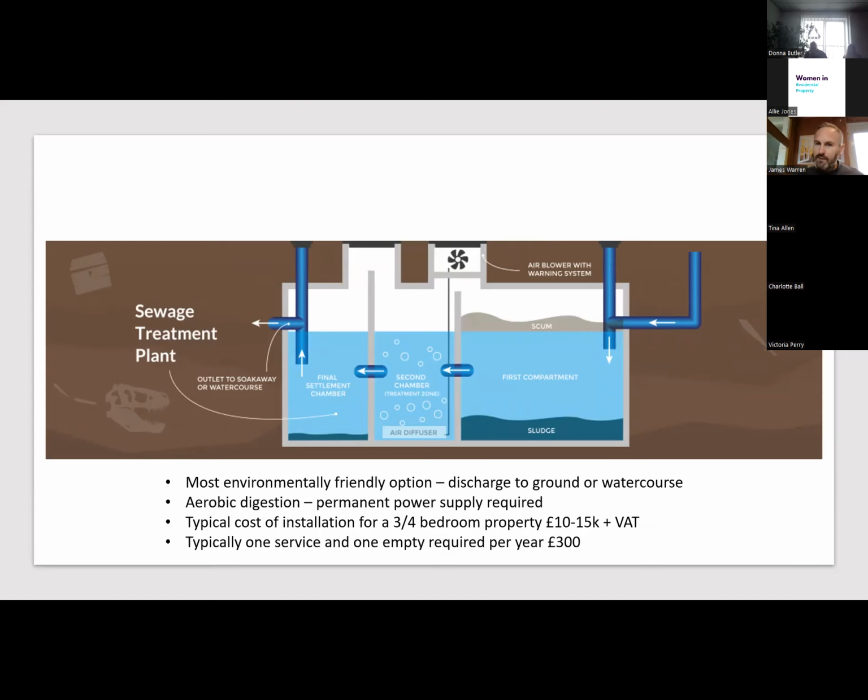And what I mean by that is, if we look at the first part of this system on the right hand side, I've labeled it first compartment. Its actual terminology is primary zone, but it's nothing more than a septic tank inside this housing. So in the good old days, you'd have a separate septic tank, then you'd have something called a clinker bed, which is where some treatment occurred, and then you'd have something called a reed bed, where it'd be natural biological assistance with the treatment process. And after that, you'd be allowed to discharge into a river, stream, or ditch.